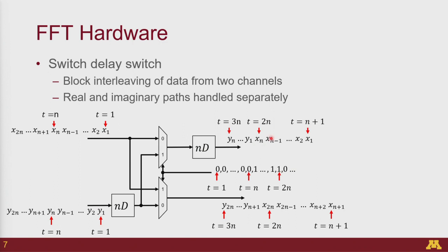The other thing you should note is that even though the system has a latency of n, in reality, when you think of it in terms of timing or critical path, this does not actually break up your critical path, because you can see there is a path which goes from the input to the output with no delays at all. So from a design point of view, if you're trying to meet some sort of timing, you should know that even though this adds latency to the system, it still does not break up any of your critical paths.